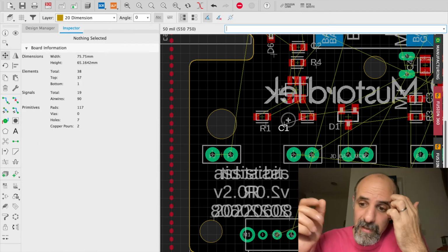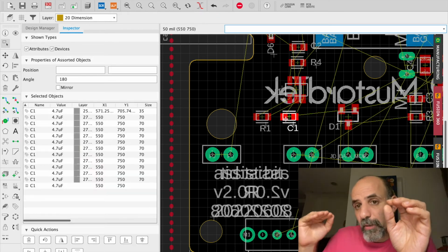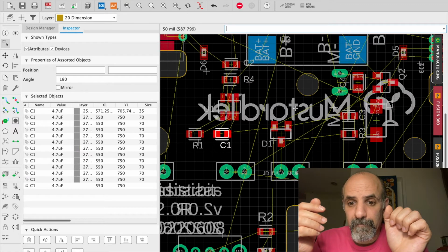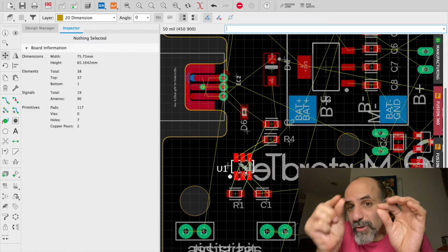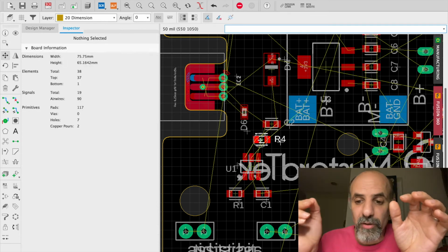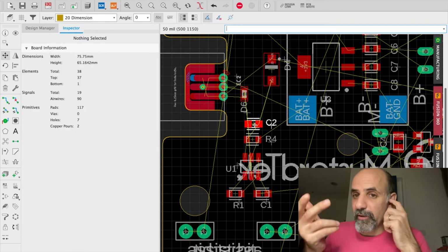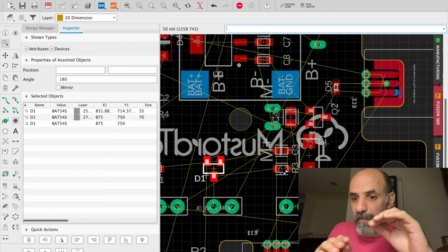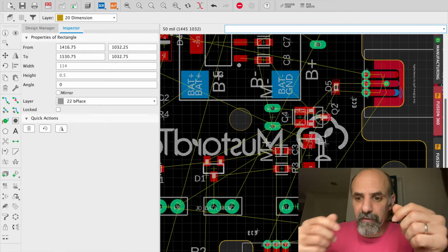But essentially, what you see in red now is going to be copper on the top layer of the circuit board, a way for you to organize the circuit. And then what is blue is going to be on the bottom layer. And then you do the cables around, and whatever you move is going to actually reflect in your design. As I have all these components, somebody wanted to make an integration of a mute function that is going to be next to a webcam. So the electronics, that's a resistor because I have an LED.